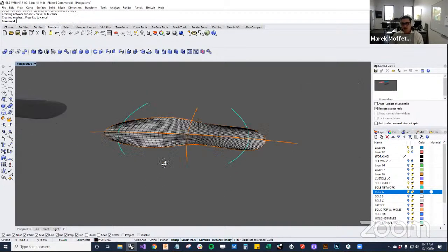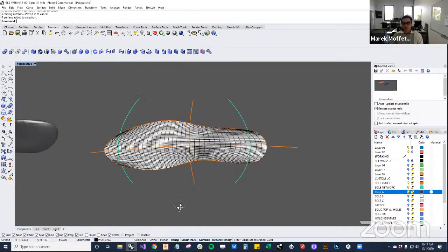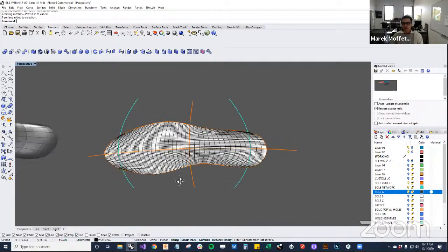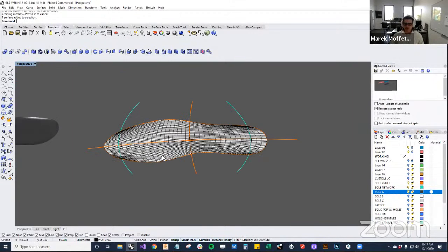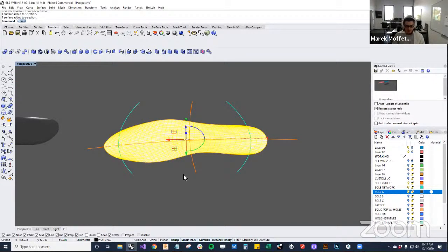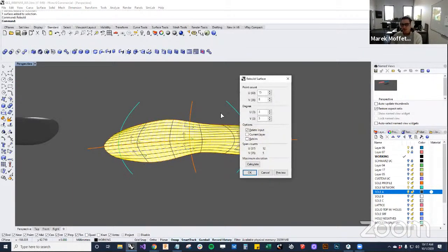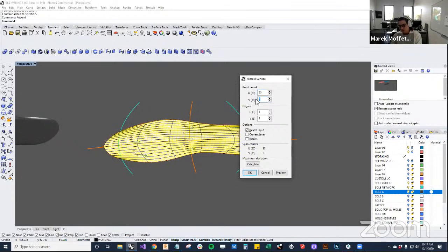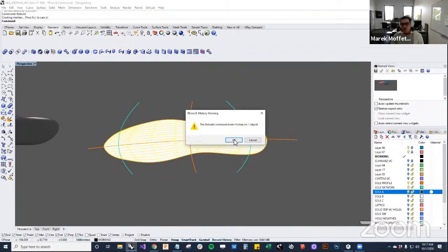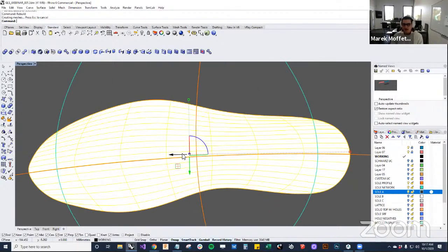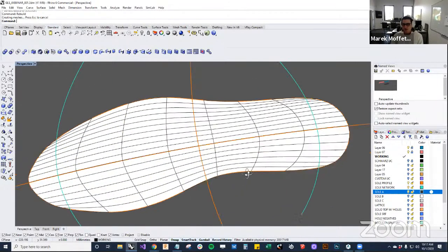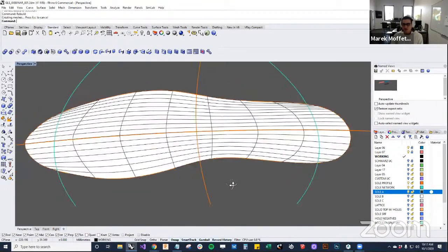And we'll hit OK. And so now we have a single surface matching this profile that will work great with our tool. And so just for the sake, I'm going to rebuild this surface. And you can see it has quite a lot of data. I'm going to reduce that because I am not too concerned with it perfectly matching that profile. Yeah, and that looks really good.